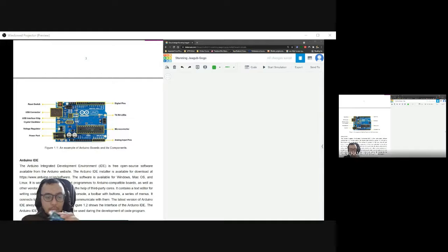And then the analog input pins are at the bottom of the microcontroller. Is it like this? Oh, something like this. This is where you get your data from. If you have thermal or temperature sensors, you connect them to the analog input pins. Power is for powering up all the sensors and motors you want to draw power from, so you get it from here, 5 volt. But we are talking only about voltage. Current comes from the voltage source, upon demand.